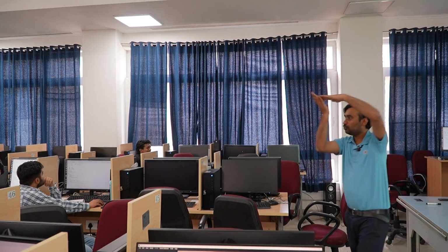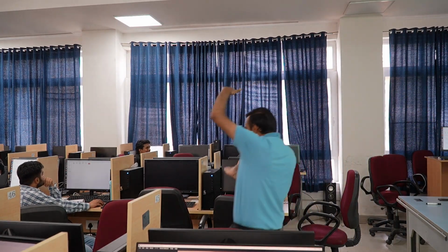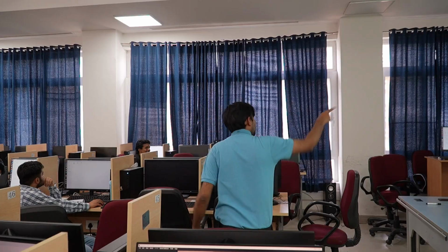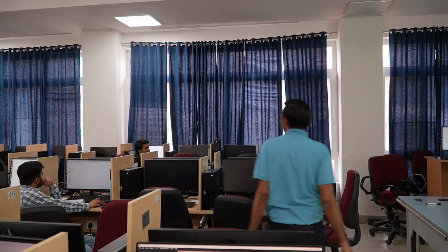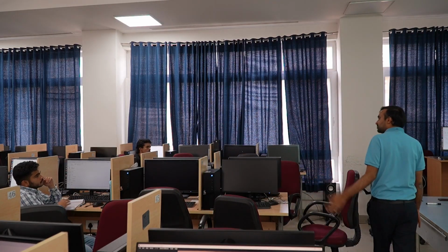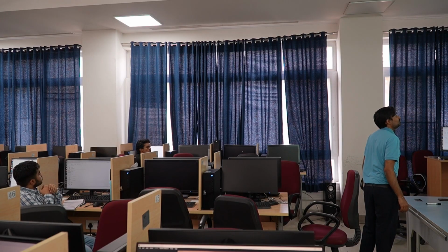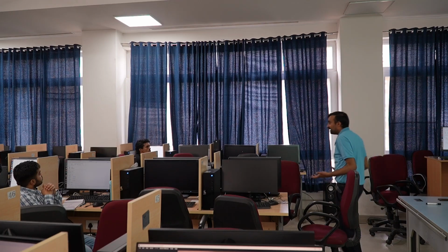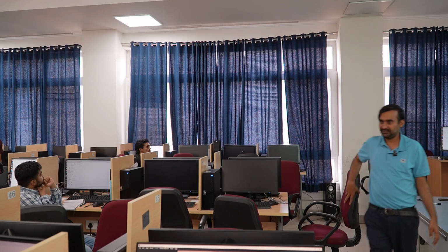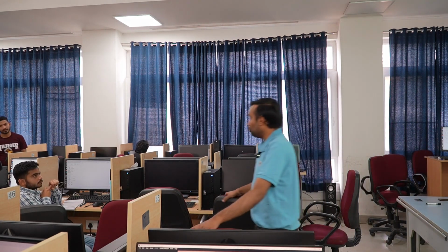My domain was extending in the vertical direction up to minus 0.2, so I am defining the center somewhere slightly above the bottom wall. And the radius of the sphere I have defined as 0.00125. What does it mean? The diameter of the sphere will be 2.5 mm. Are all clear with this?